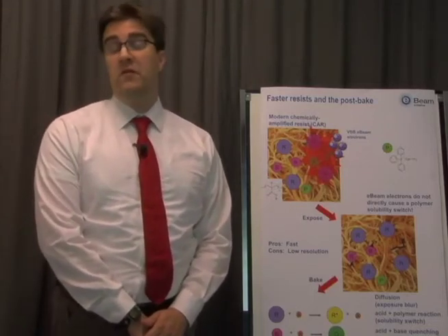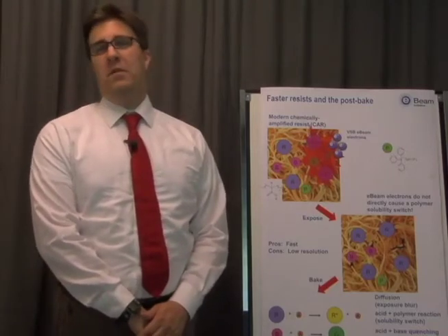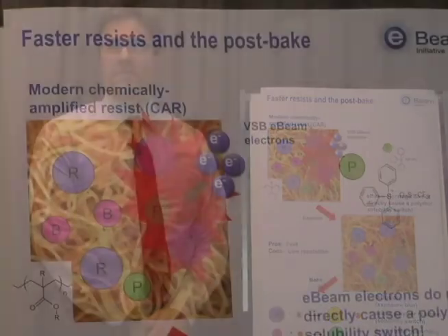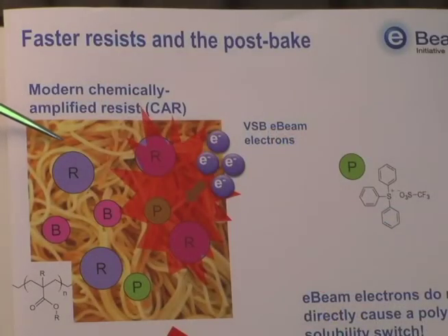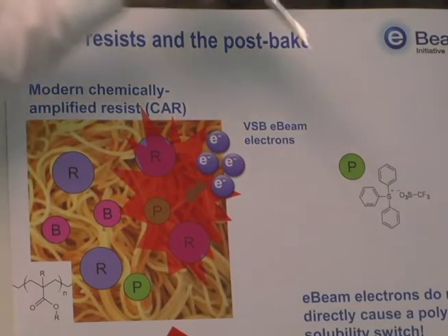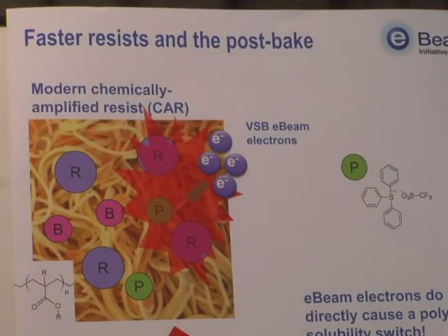So what the mask process engineers had to do was to take a trick out of the wafer fab process playbook and introduce something called a chemically amplified resist. Such a resist is much more complicated. In addition to the polymer reaction sites, other additional materials are also included in the photoresist, the most important of them being the PAG, or the photoacid generator. These are designed to significantly reduce the number of electrons required to print a mask feature. We'll see how that is shortly.